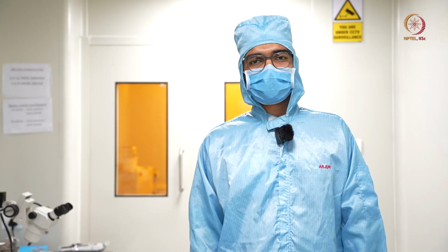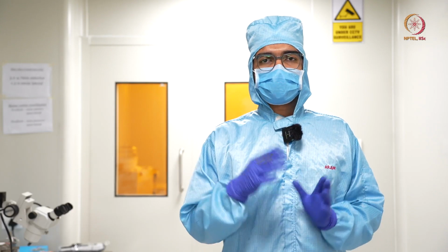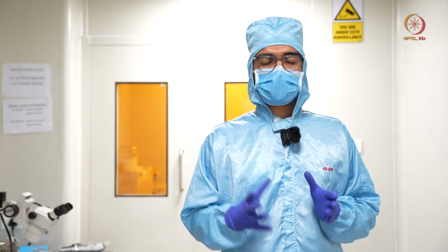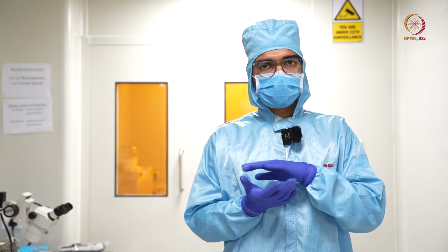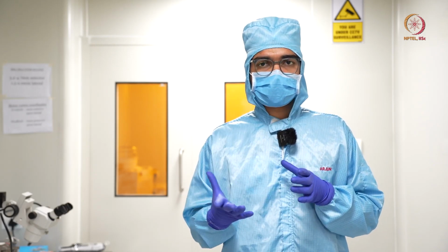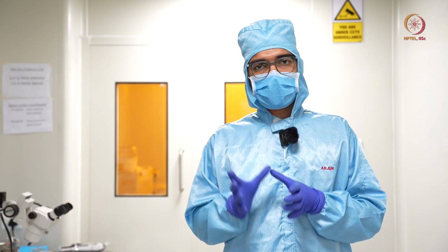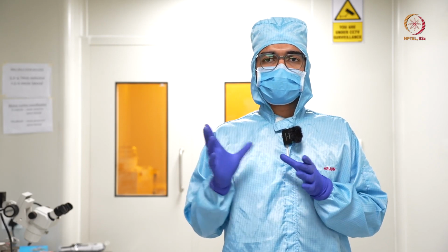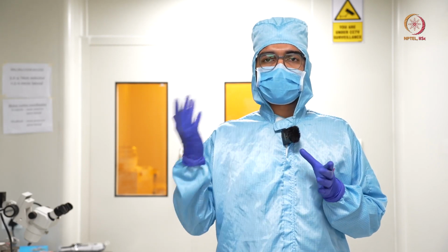Hello, good day. We'll be discussing lithography today. Okay, so you might have already seen the processes where we have a silicon wafer on which we might have spin coated a thin layer of polyimide, which is a flexible substrate, right? And it's baked and cured so that it can be used for the next step, which is electrode fabrication.